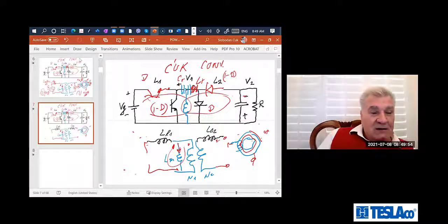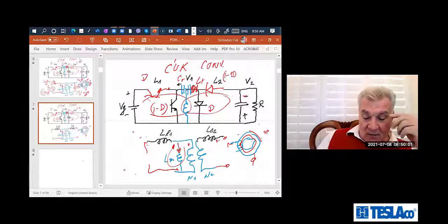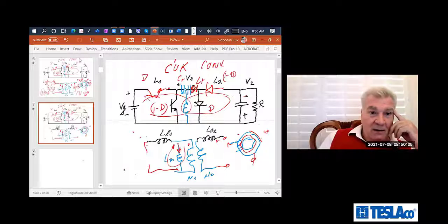However, 60 hertz people used a model of a transformer where, if you reflect the secondary inductance on the primary, then you can have a model with LL1 plus the turns ratio N1/N2 squared times LL2, let's call this LL2 reflected.